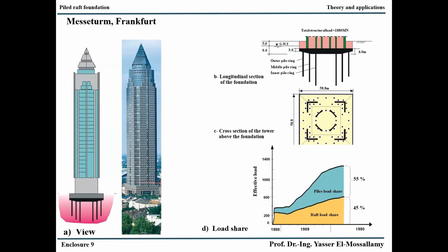And without any very complex calculation analysis, but only from the observations that one has taken by the Torhaus, one has said, okay, if the piles at the edges attract more load due to this distribution at the edges, then we make the piles at the edges shorter than the piles in the middle, so that we try to have the piles more or less with the same stiffness.